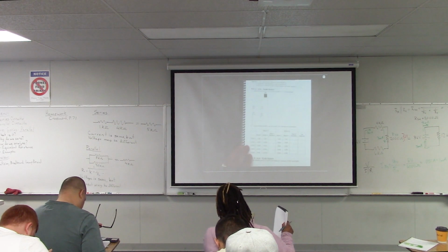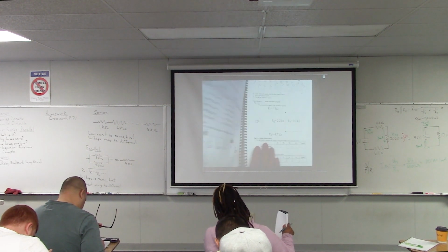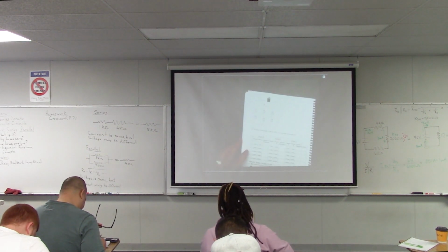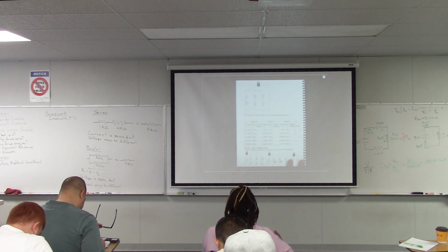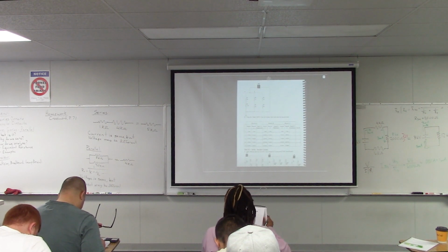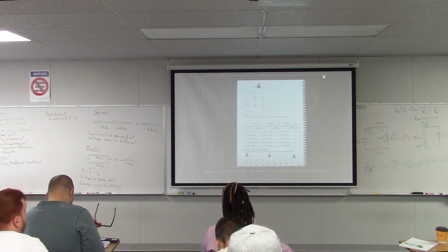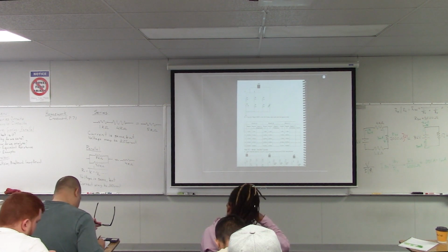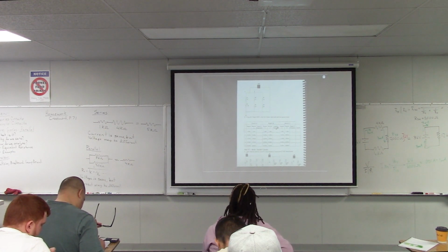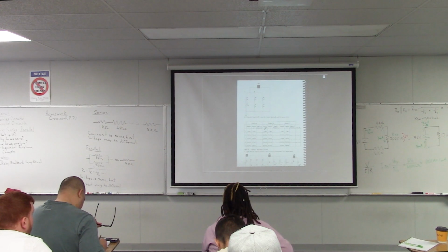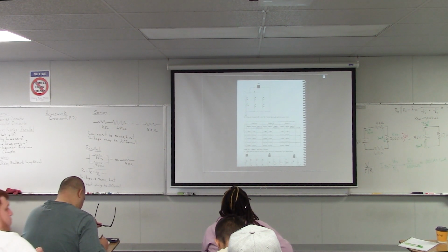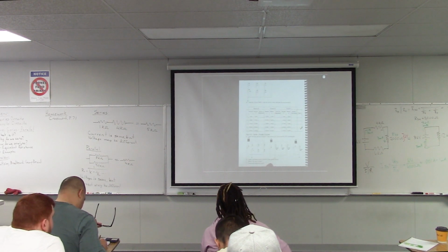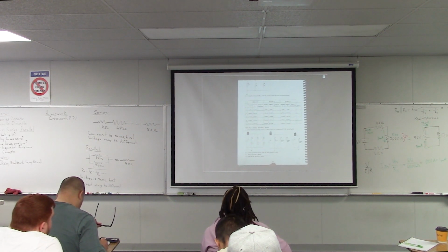All right. So then the next part, you would open this circuit in Multisim. Very similar, but now we have 3 branches instead of 2. Okay, so you do the same thing. You calculate the resistance for each branch, and then you use Multisim to measure the total resistance there.